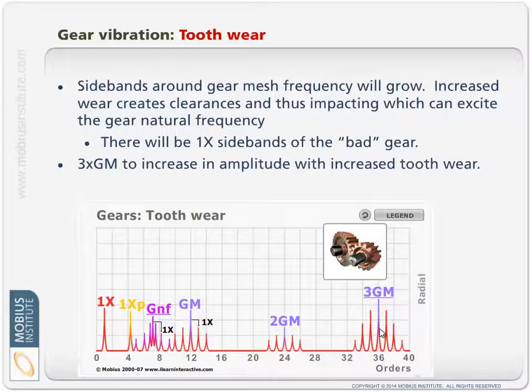and tell you, yes, wear is occurring. So yes, vibration may be an indicator. Ideally, you would have already been doing oil analysis, and you should be getting warnings from that technique as well. But every additional piece of supporting information you can get is always helpful when you're making a call like this. So obviously with tooth wear, there should be clear signs in the lubricant. The root cause may be also present in the lubricant as well.